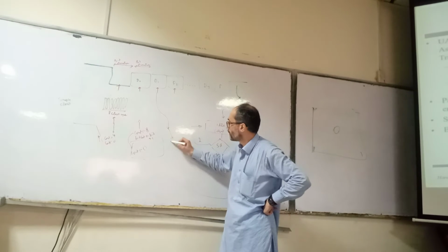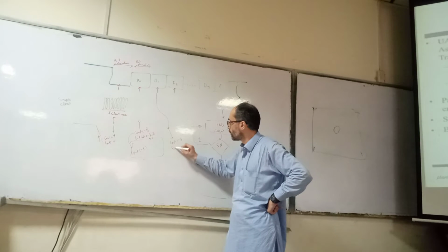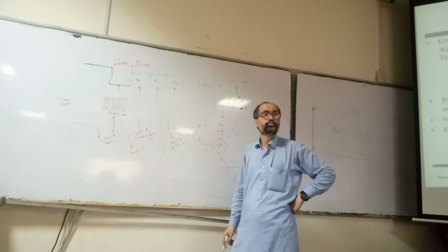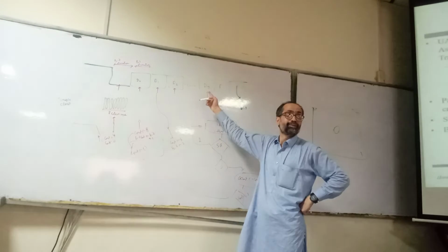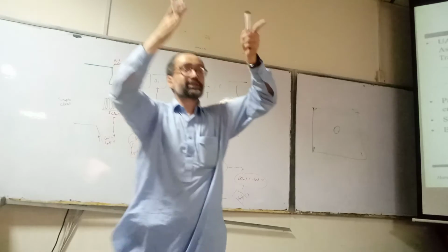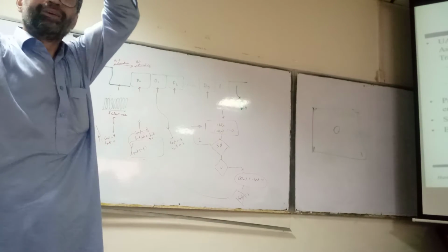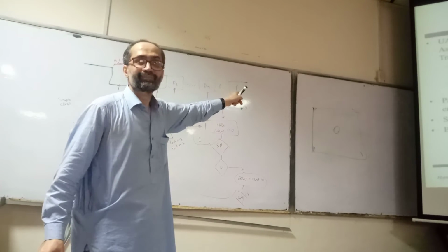In this case, what will be the value of count? When counter reaches 8, what will be the bit counter now? 2. When will we sample the last bit? When bit count is 8. So actually now we have reached the middle of the last bit. And when will we reach the middle of the parity bit? After 8 clocks.